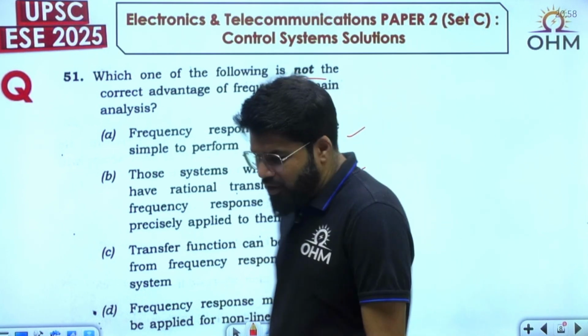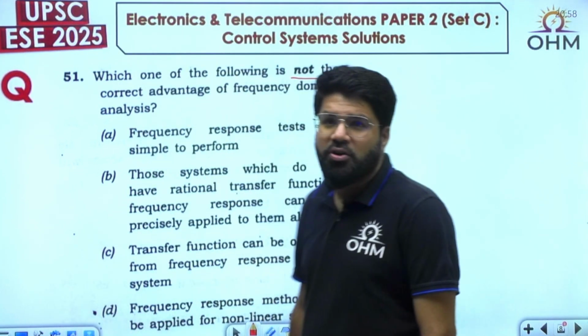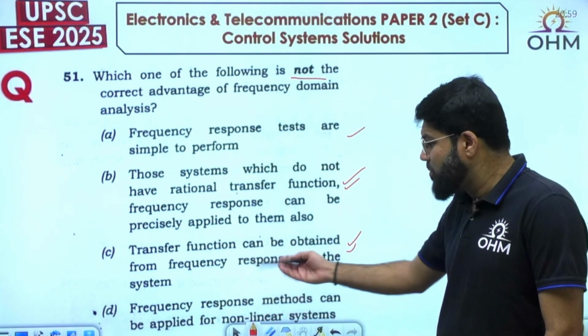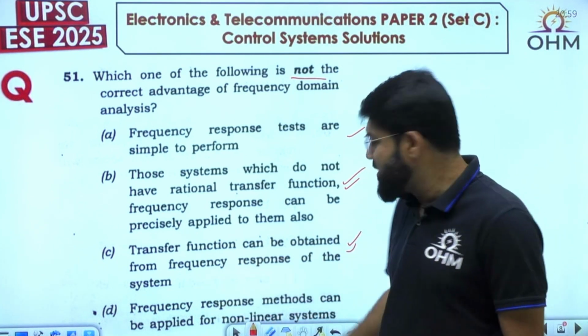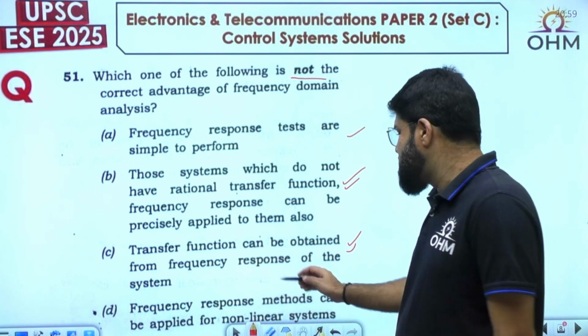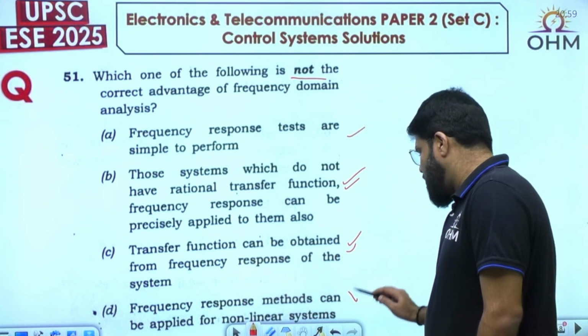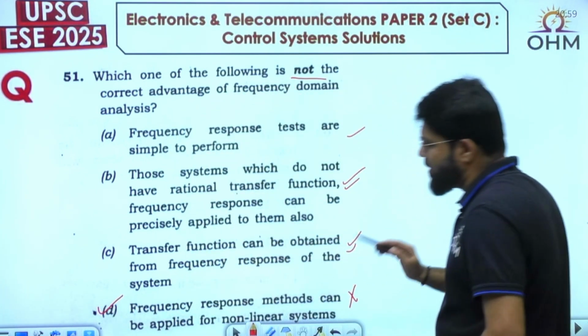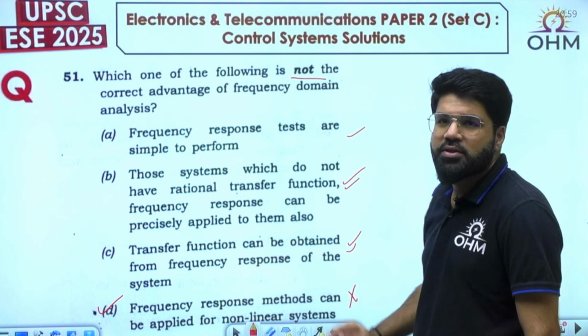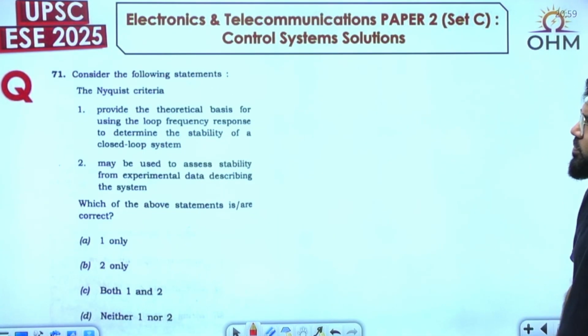No. All this transfer function or frequency response theory comes up with the help of convolution properties. Convolutions we know are applicable for LTI systems. Hence, frequency response methods cannot be applied for non-linear systems. So D is the not correct answer. We have to choose the not correct answer, so we'll choose D.